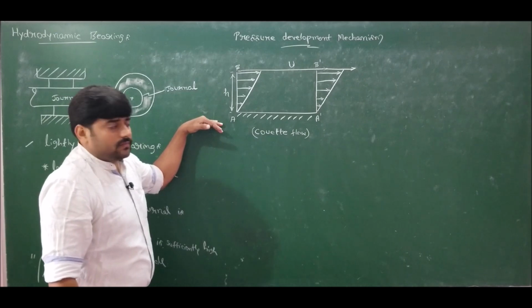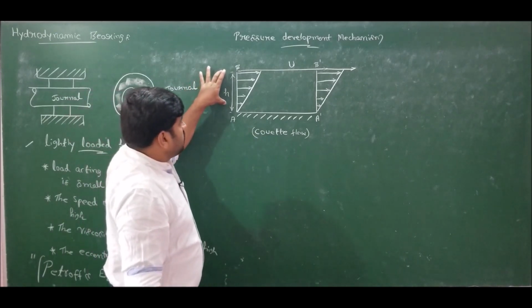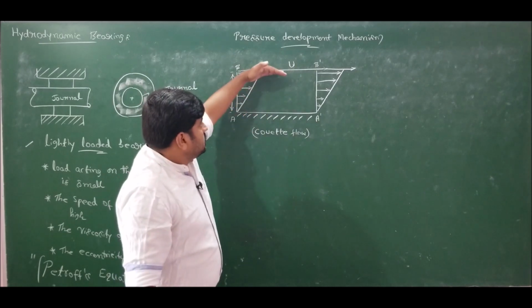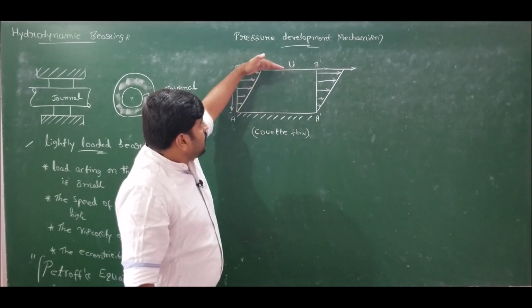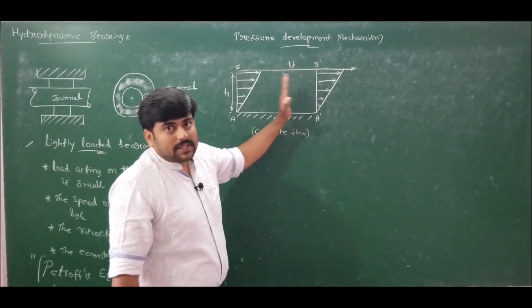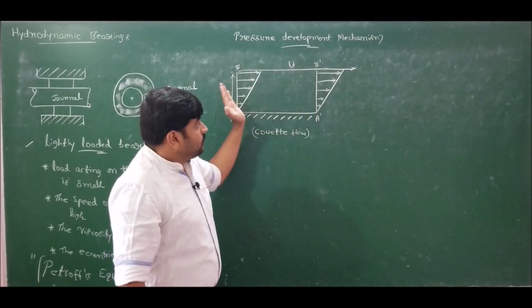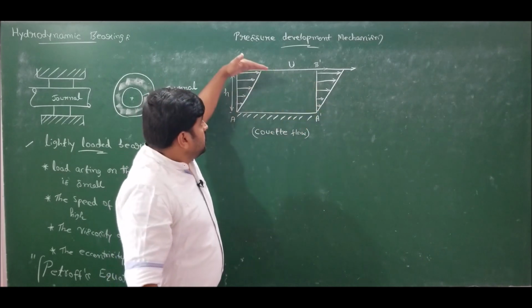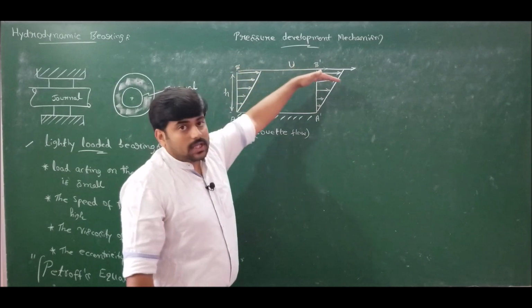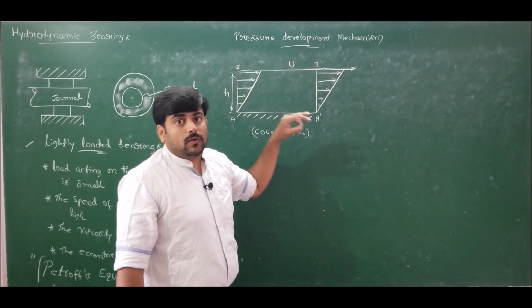If you carefully observe, at any point on the fluid film between the two surfaces, the pressure remains constant. The flow is happening only because the top surface is moving. Such flows are termed velocity induced flow.